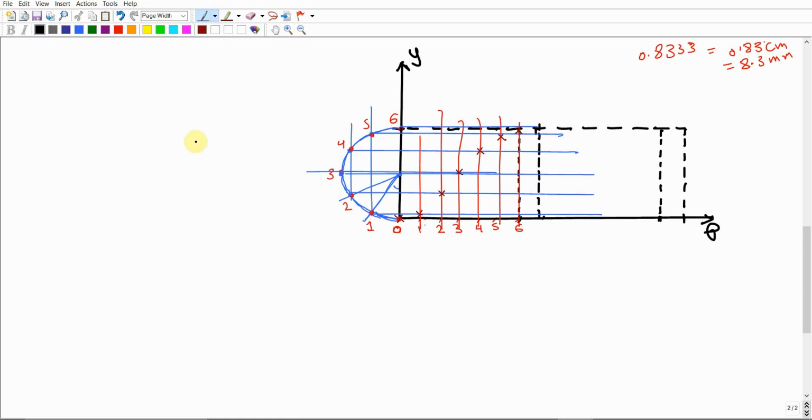Then your objective is just to connect these points together with a curve. So I'm just gonna connect these points together by hand. You guys try to connect them, and take it easy as I'm doing, as much as you can. This way. I'm sorry, it should be like this, up to this point, right? So this is gonna give us the first curve, the first simple harmonic motion. It's gonna be this curve as we already got it here. Make sense? Then after this simple harmonic motion, we should have here a dwell period. So there should be a horizontal line here representing the dwell period.